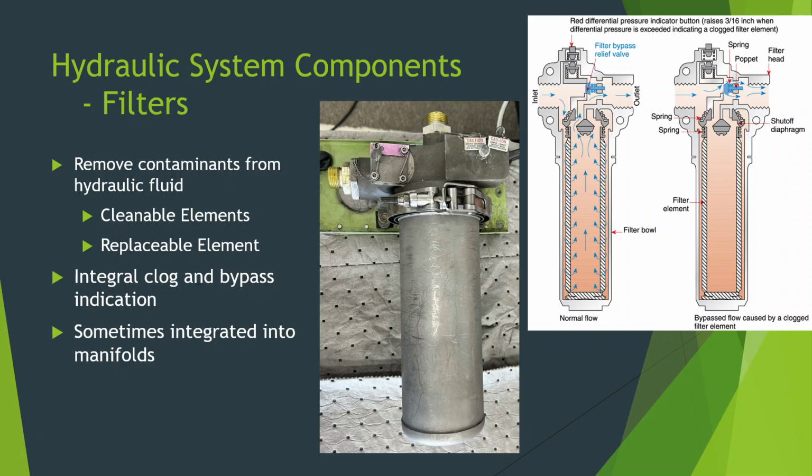But remember, these systems are running at 3,000 PSI. You can't just have a paper filter like your engine oil filters, which are paper but not reinforced at all, because they're only holding like 30 psi, 50 psi, 80 psi on my boat yesterday. It was running a little high, I think, because it was cold. But at 3,000 psi, a paper filter is just going to blow out unless it's supported somehow. And so they're still screened. They still have a lot of metal, but they are a replaceable filter. Ultimately, the filter element is cellulose based.